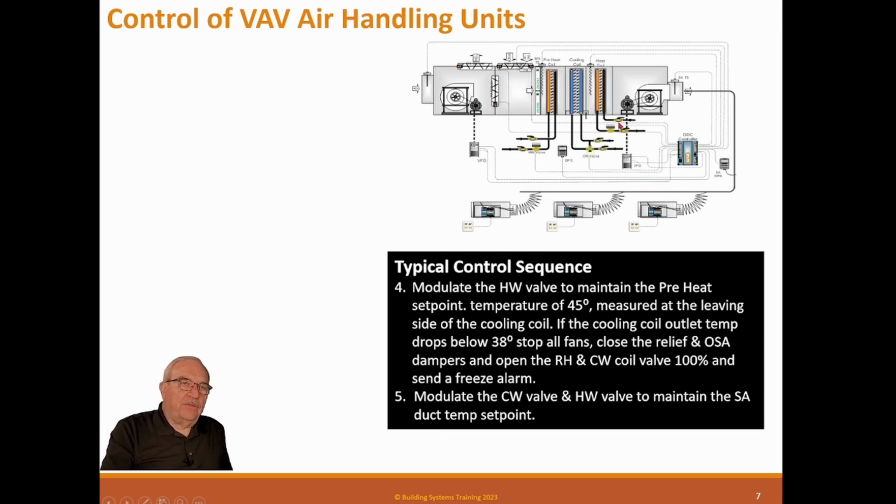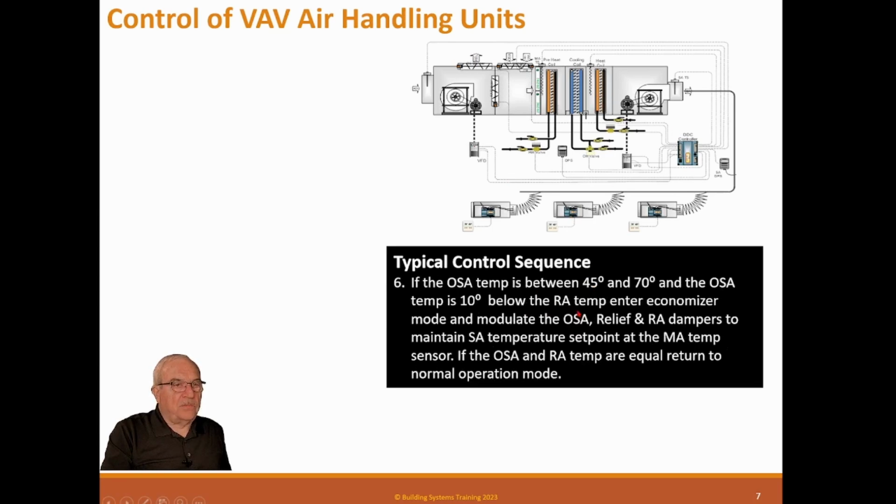And that is, if you don't have heating in this system at all, you just have a cooling coil, you have reheat coils on most of these boxes, but you have some that are interior boxes that don't have a perimeter load, so they don't really need heat. So what happens here is if you have this one without a heating coil, and this air is 55 degrees, or say it's been reset up to 60 degrees, it still may overcool these boxes without heaters because they have a minimum ventilation set point. In other words, that damper is not closed. It's slightly open to give ventilation air to the occupants. So when the air handler doesn't have heat, it requires a special reset sequence.